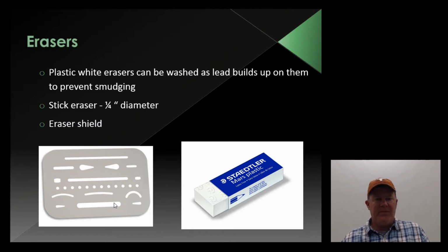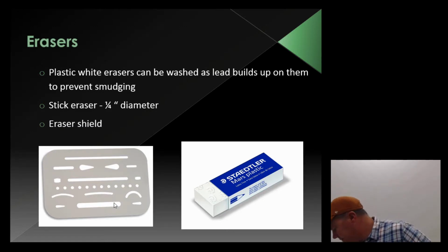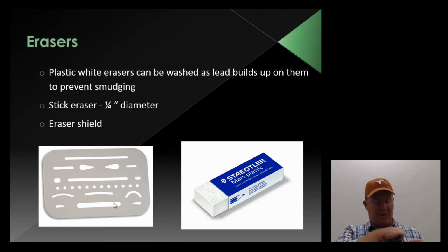The plastic white erasers can be washed as leads build up on them. So basically, yeah, you can just wipe that down good with a wet paper towel. Stick eraser, 1/4 inch in diameter. Use these, keep in your pocket and stuff. But if you're using pencil, that's good. These are even good for ink, especially if you have the blue Stadler. And you'll have one that'll be white on one side and blue on the other side. One's for ink on Mylar, the other one's for pencil on Vellum. So you can use those hand in hand.